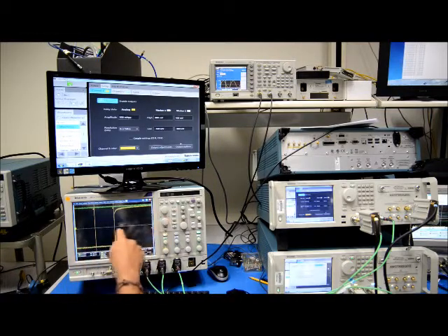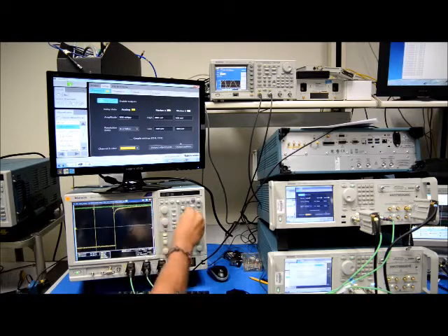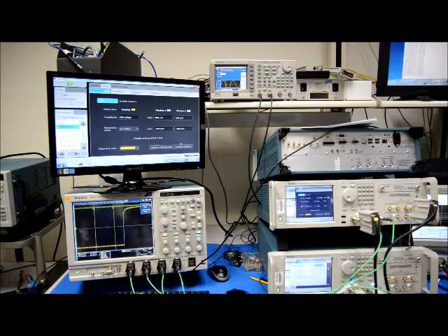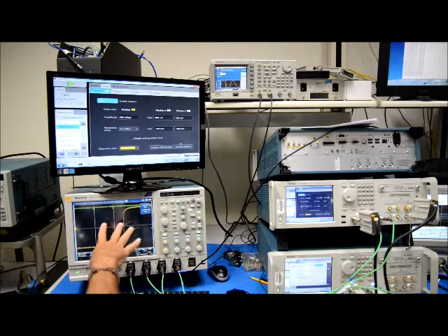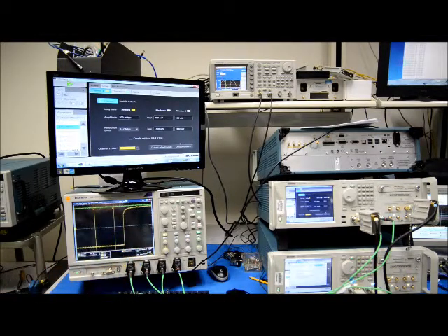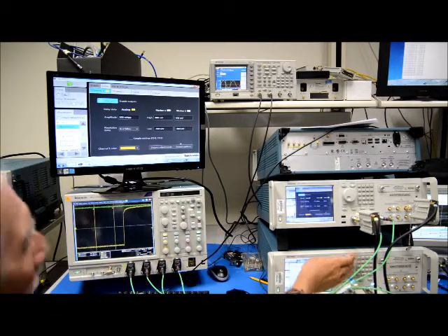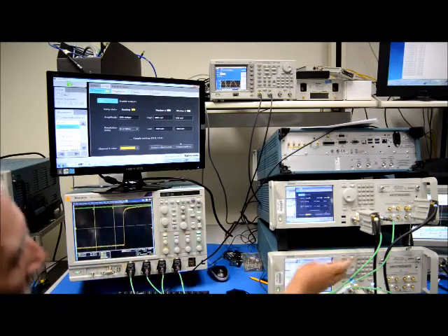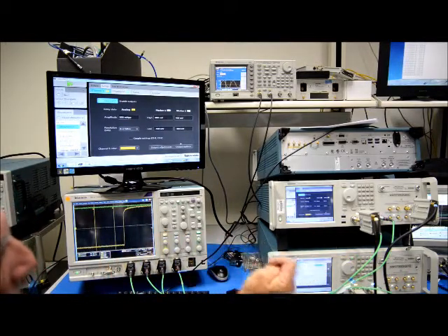Now what we're seeing here is we're triggering off of channel 1, and if we position this, we can see that the AWGs did not align very closely on the outputs. So this is the time-consuming part, in the sense that we need to repeat it again and see if we can get these two edges very close, within 2 nanoseconds.